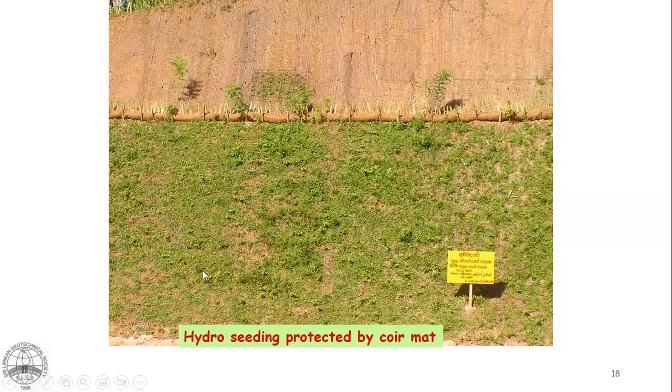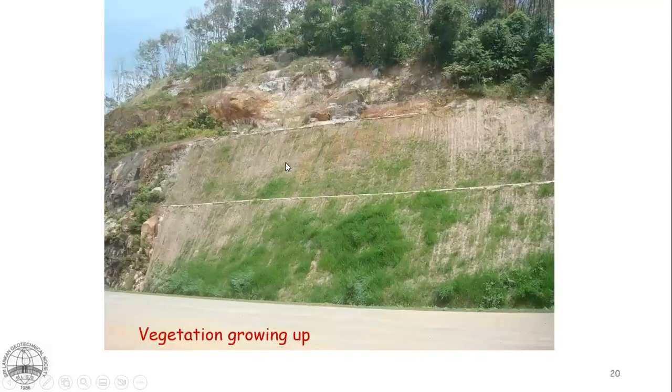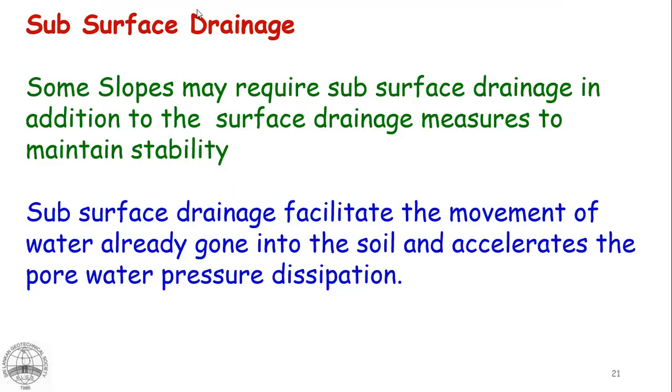So this is hydroseeding used as a surface protection device with this wire mesh there. And this shows the hydroseeding done with a straw mat, right? So the hydroseeding had been done and the surface had been covered by this straw mat, and they are doing controlled watering till the seeds germinate. So you can see a later stage where now the vegetation is growing up, showing up. Right. So those are surface drainage measures.